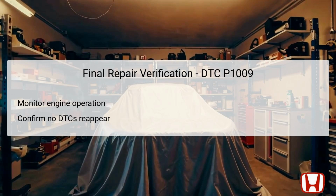Check for responsiveness and performance, confirming that the intake camshaft is operating within its specified limits. Additionally, you should run the vehicle through multiple drive cycles where the conditions for the DTC's monitoring are met to ensure that the PCM does not register the DTC again. If the check engine light remains off and no new codes appear, it indicates that the repair has been successful.